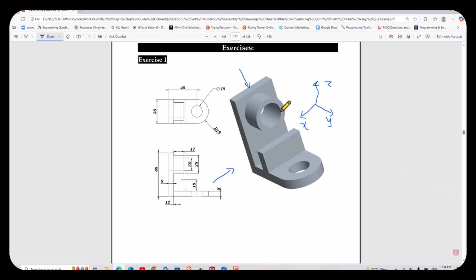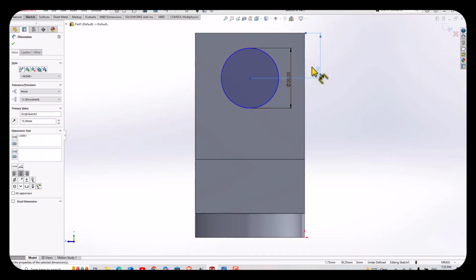So that means that if we are sketching the inner circle and the distance from this side here to this point on the circle is 5 mm, then the distance from this edge here to the center of that circle should be 5 plus 4 plus half of 20. So that is 5 plus 4 plus 10, giving you 19. Okay, let's go ahead and specify that.